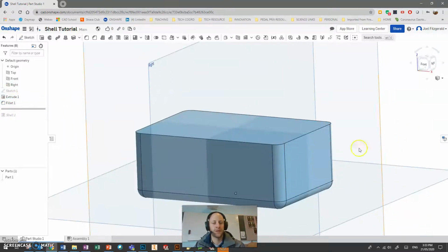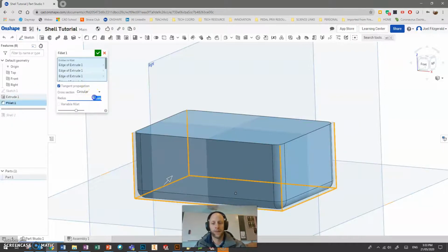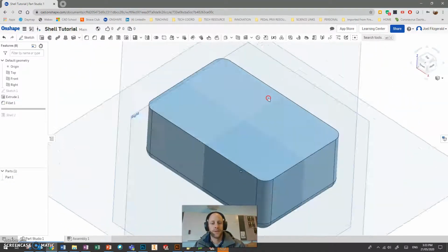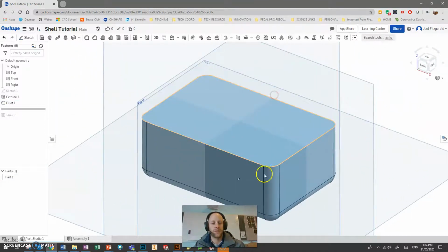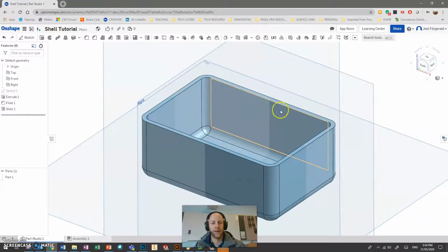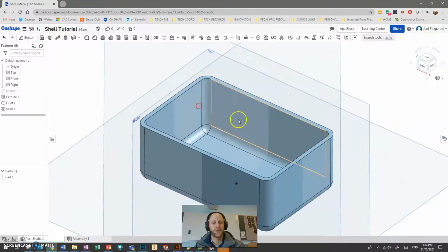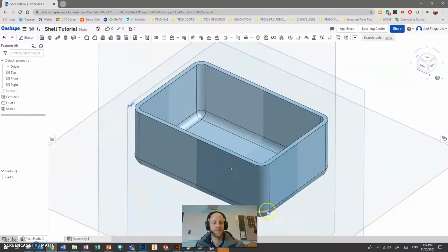So you fillet the main body. I'm going to now change this back to 5 mil because I can. Click on the tick. So things like fillets, you've got to think about putting them in before the shell tool, because the shell tool is going to hollow everything out on the inside like that. So that is much simpler than having to try to fillet all the inside lines and things. Don't worry about doing that. Fillet first and off we go.